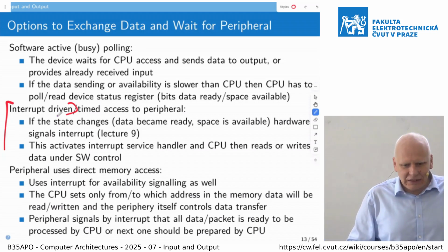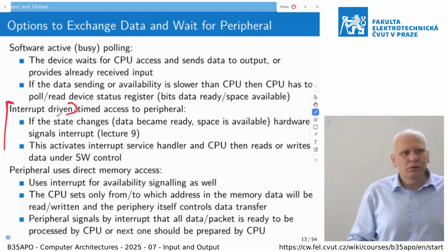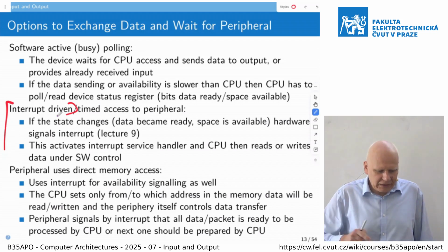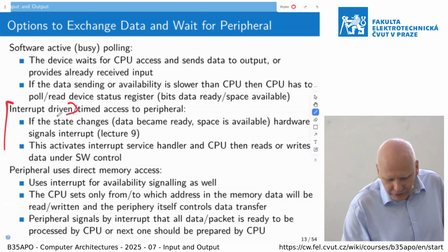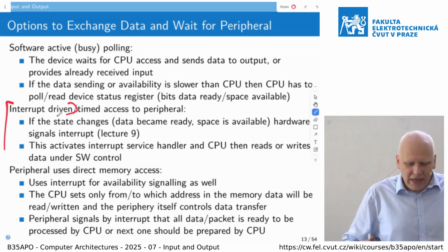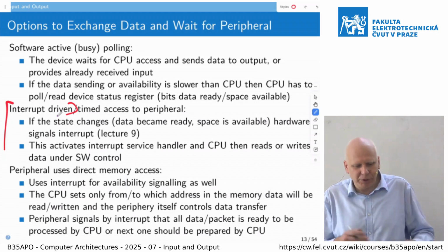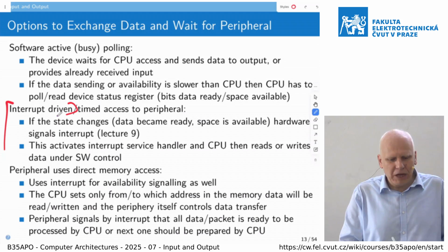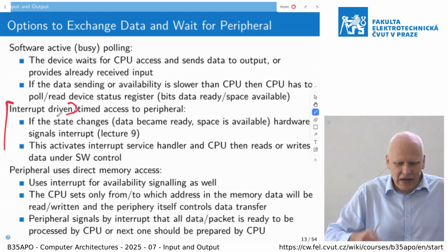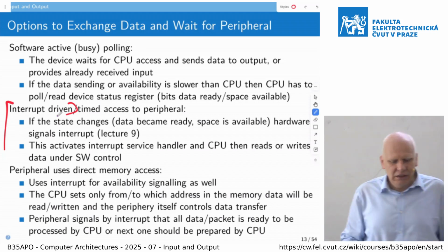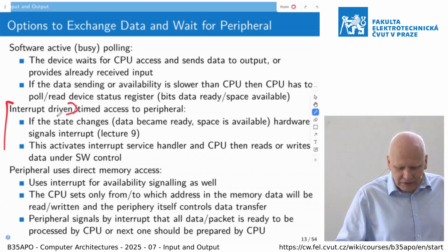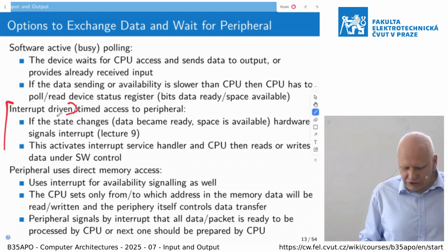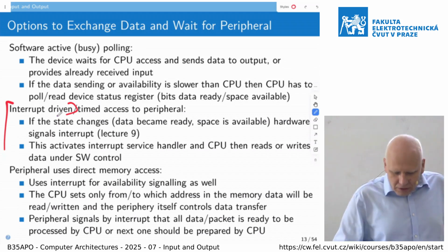This results in the switch in the processor to the interrupt service routine or interrupt handler, and it can process that operation. The actual task which processes the input can be stopped by the operating system, and when the new data arrives, it starts the task again and releases it to continue and process the data and prepare a new state to display on the screen, and so on. Okay, so